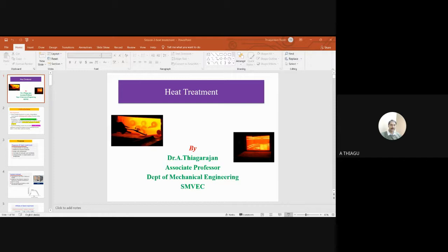In the full annealing process you can select hypoeutectoid steel. Hypo means the sample should have less than 0.8% of carbon. It should be heated 30 to 60 degrees above the upper critical temperature, in the range of 727 degrees to 910 degrees centigrade.